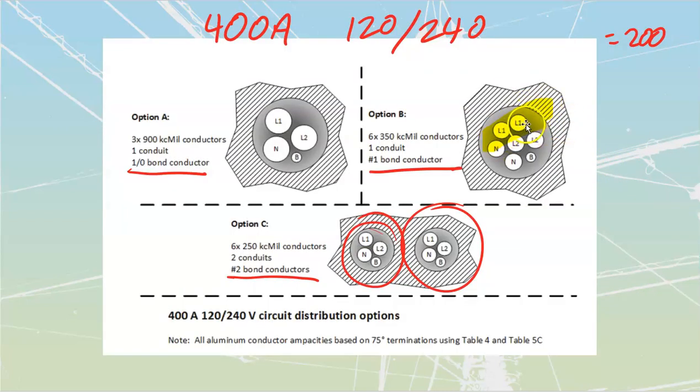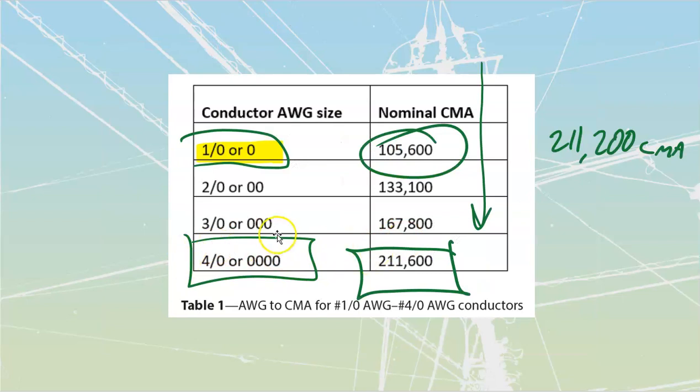Okay, so if I were paralleling those inside of a conduit, if these were 1/0s inside of here, I would have to use the lookup out of my Table 16. That would be a lookup for a 4/0. What they give you for math down below, 4/0, it would be given as 180 amps. And so you'd have to use the not exceeding. When you do the not exceeding 200, using a 4/0 AWG of 180 amps, then what you would find is you could use that same number 4. Once again, it lines up. The 2015 and 2018 give us the same results. They just give us different methods of getting there.